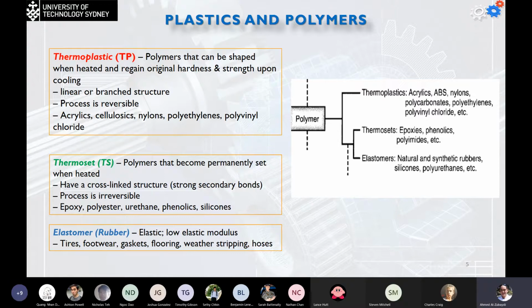The other type is the thermoset, which is going to be the opposite way. It's going to be solid when it's heated up. An example for that is the epoxy. So usually it's going to have a chemical process to make it liquid. When it's mixed with the other agents or with the catalyst, it's going to have a chemical reaction and start to release some fumes, and thus it's going to start to solidify until it has the final shape.